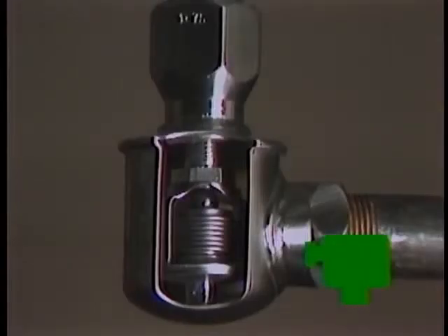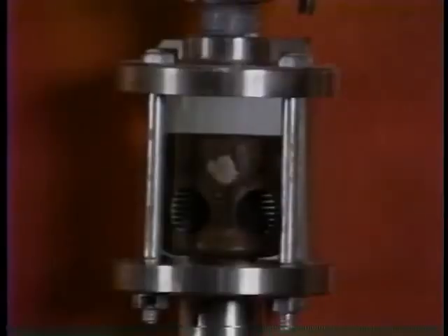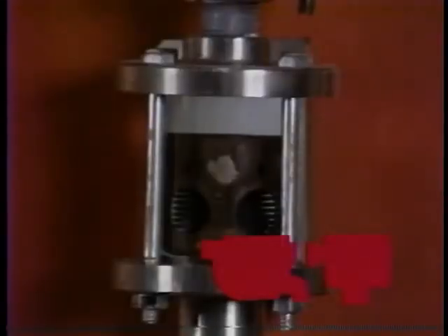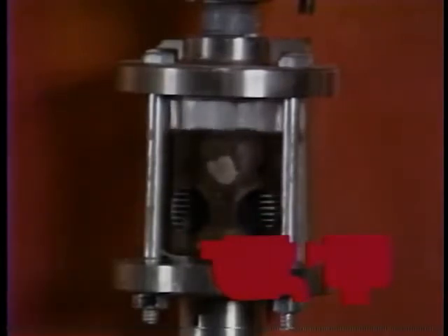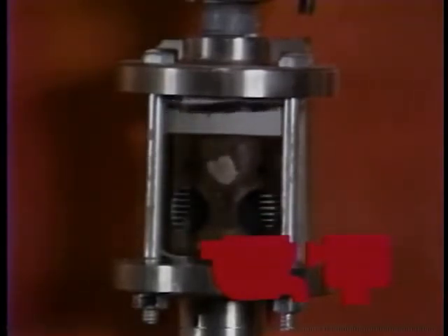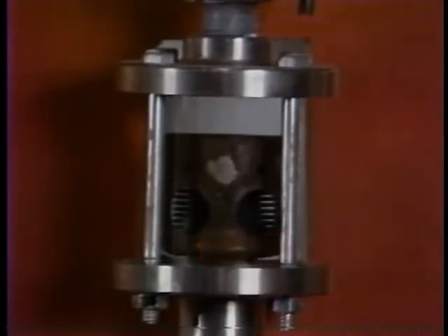The bellows trap may be oriented in any direction. When the valve is located at the top, this trap also resists clogging. Since the trap modulates on low loads, however, care must be taken that dirt large enough to lodge in the throttled opening doesn't enter the trap. The bellows trap in any other orientation and the F&T trap have valves in or near the bottom where dirt can accumulate, blocking the orifice. In addition, the small openings, when these traps modulate, are easily blocked open or closed by small dirt particles.